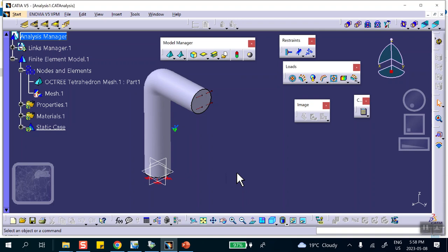Okay, good. Now, so what did we do? We created the geometry. It automatically meshed it for us. Remember, we needed a material. We had to put a material on it. We use restraints. We use loads. You're going to be doing this for the next 6 weeks. And then when you're done, you say compute. Compute, right there.